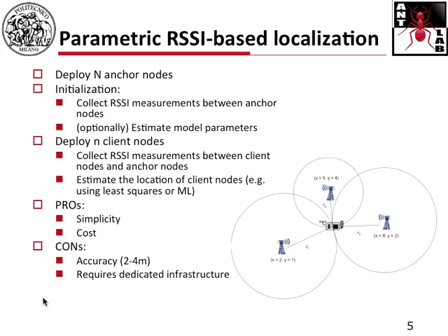Okay, so what are the advantages and disadvantages? The advantages of this kind of parametric RSSI-based model are basically simplicity. It's very easy to implement. You can do it even with off-the-shelf Wi-Fi hardware. And cost: you can do it with very simple and naive transceivers like ZigBee, Wi-Fi, and so forth, which cost very few dollars or euros.